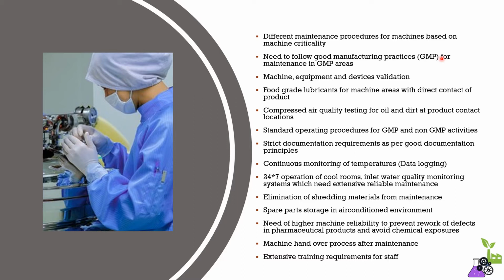So imagine a maintenance technician coming to do a maintenance activity in such an area. Even though it is maintenance, still he has to comply with GMP. They cannot do maintenance activities as in an outside workshop, because a normal engineering workshop is quite dirty and messy, and the environment is totally different from a manufacturing area, a GMP area. Here they need to comply, they need to wear the same kind of attire, and their footwear should be clean. Even after completing the task, they need to clean the area and properly hand over the equipment to the person who is in charge of that area.